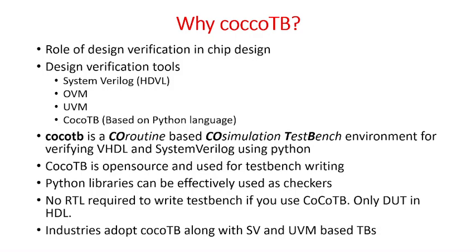And then in the traditional approach, we write the RTL with either Verilog or SystemVerilog, and the testbench also in SystemVerilog. Now we can write the RTL in either Verilog or SystemVerilog, whereas the testbench can be developed using the Python environment. That is also one important aspect. I feel that the time taken for developing the testbench with the CocoTB environment will be much easier compared to complex test case development with the help of UVM or SystemVerilog.